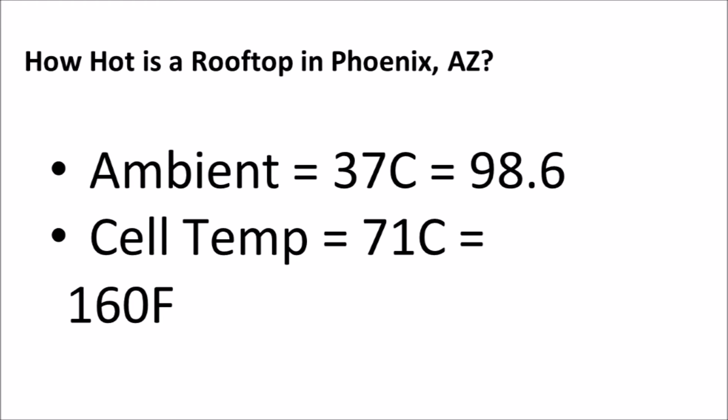It provides ambient temperature and module temperature, and it shows how to convert from ambient temperature to module temperature. But the standard test condition is done at module temperature. And so at a 77 degree Fahrenheit module temperature, the standard test condition is equivalent to the temperature of a 60-degree day outside, which is not very typical weather for most of the year.